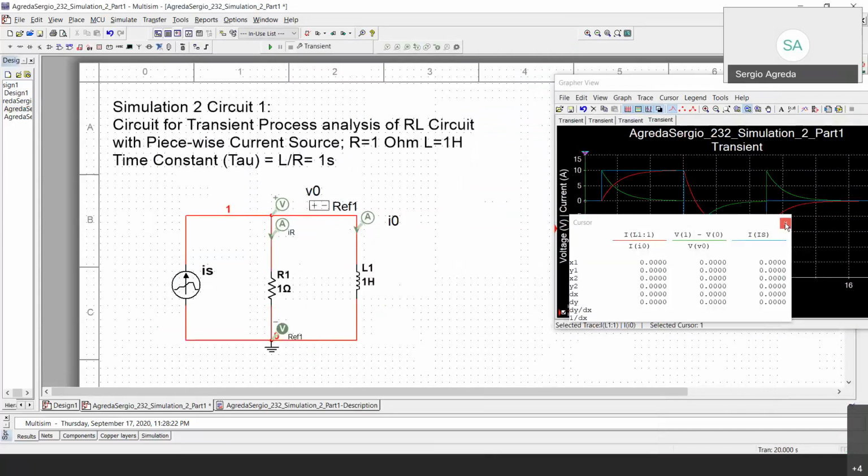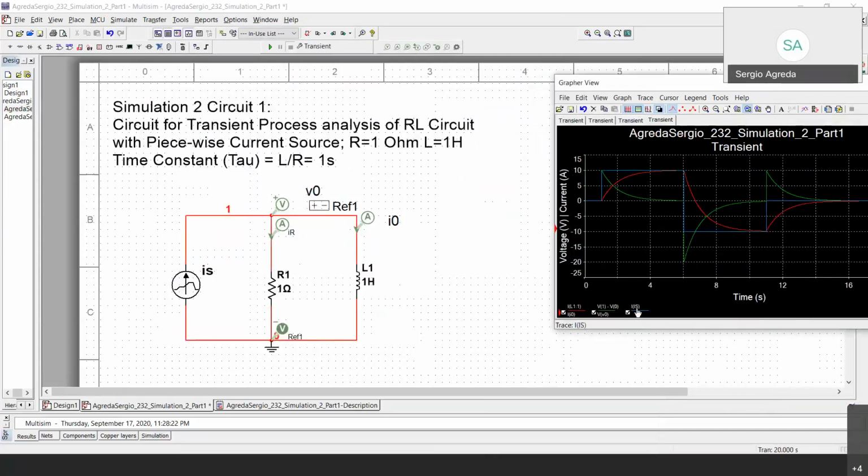So we can already start looking at what our outputs or graphs are and what they represent. For the green, these represent the voltage. You have to think about it in a circuit analysis way, that it's following the rules and laws of physics and circuit laws. Knowing that an inductor becomes a short at the end, the voltage is going to start decreasing, because more current is going to go through the inductor, but the resistor is not going to receive any current.